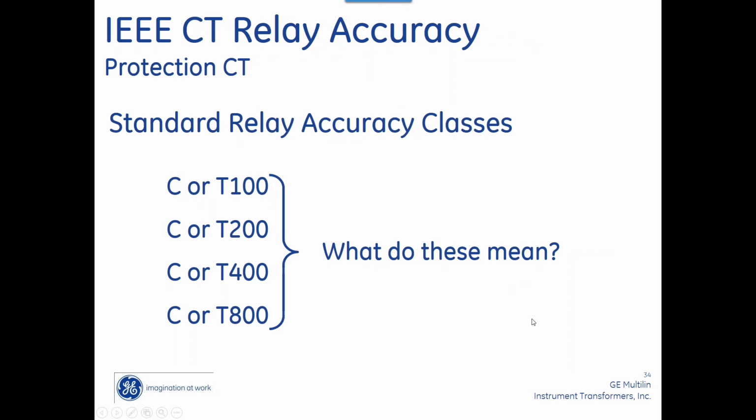Okay, are there any questions? So you should size CTs based on anticipated load you will see. It's one of the questions Spencer asked me. It depends on the application, and I'll get into that more.